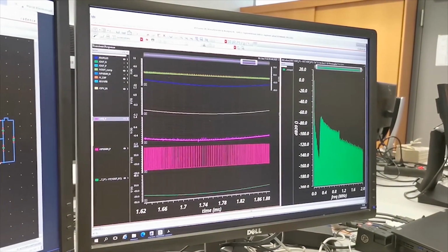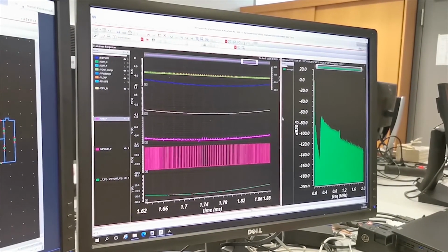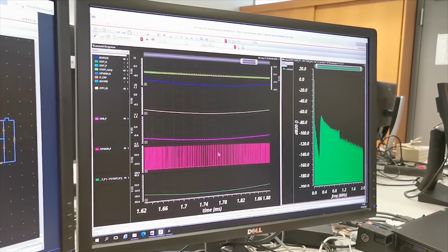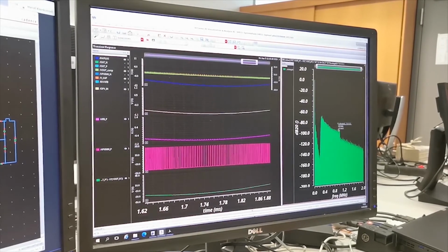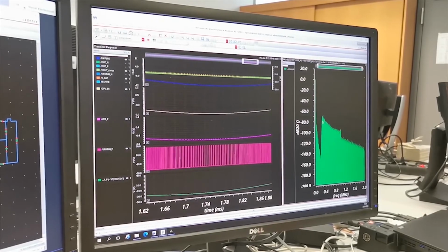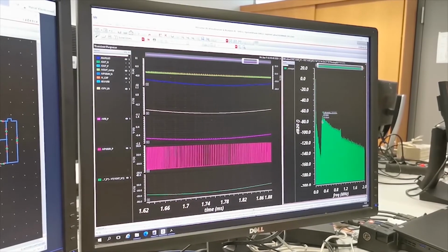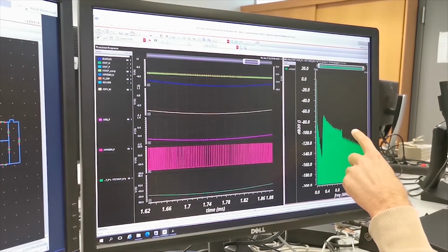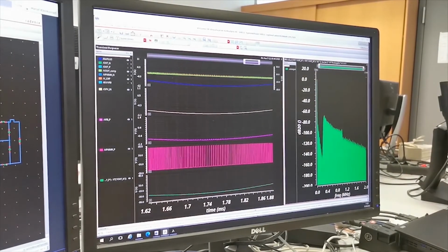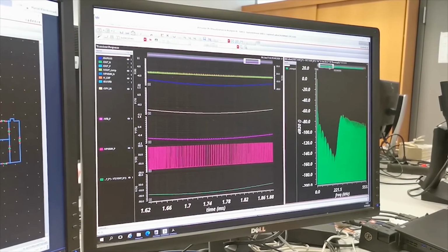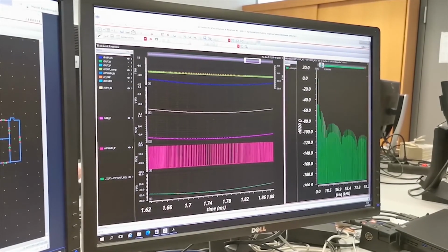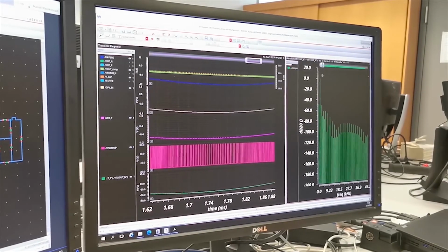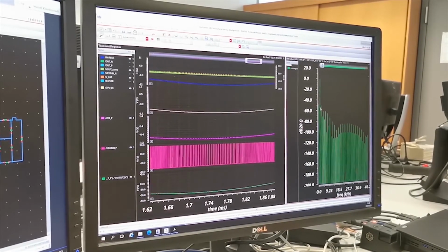Looking at the DFT, we see switching frequencies of around 1 megahertz, which is here on the right side, down to 250 kilohertz, which are highly attenuated by our low-pass filter. It's around 70 to 90 dB. And in our audio baseband, which is up to 20 kilohertz, we see the desired input frequency of 1 kilohertz.